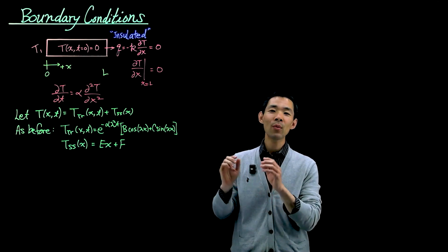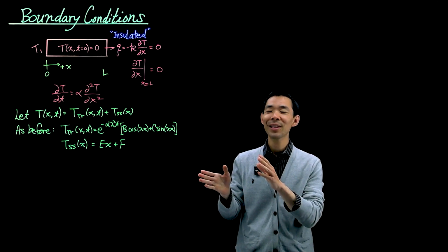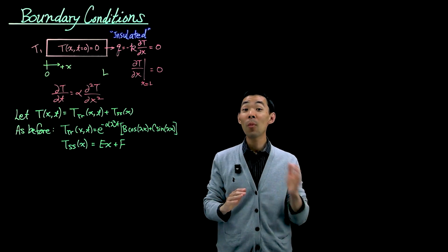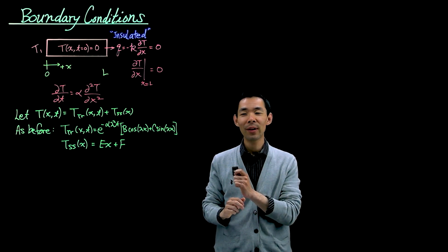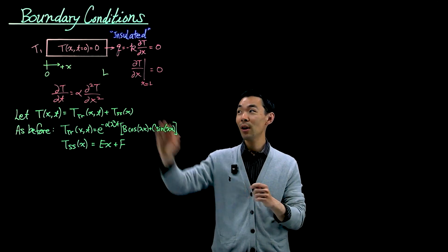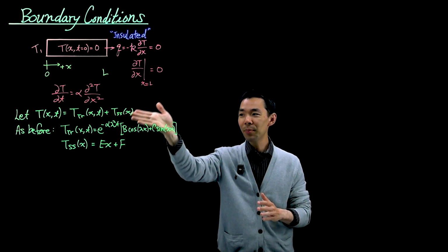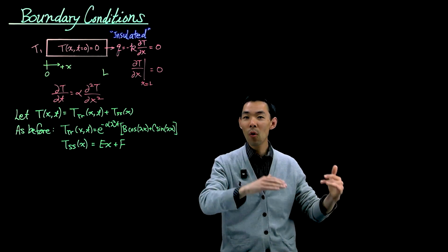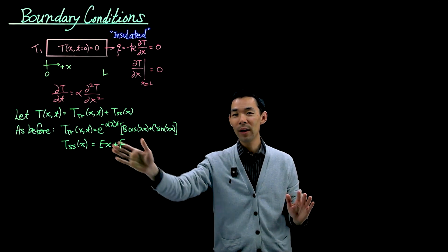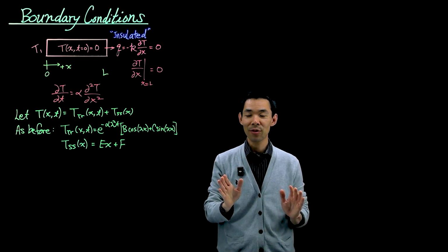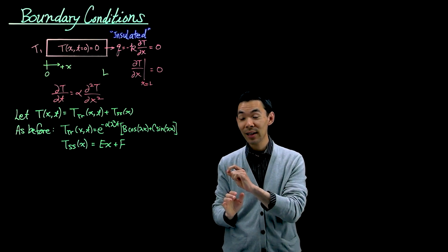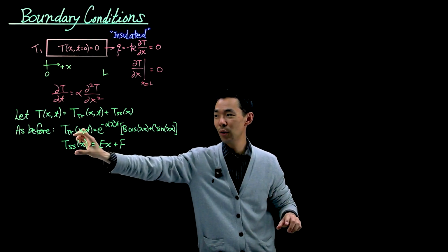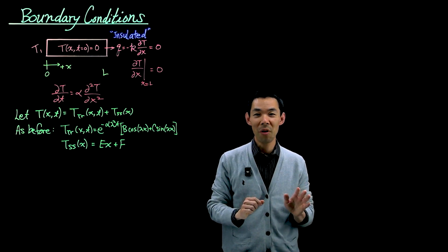Once again, the reason we're able to just write down these solutions is because the governing equation written right here has not changed at all. If you go back to your notes from the very first time we solved the heat equation, to the last lecture where we solved it for the non-homogeneous boundary condition, up to the stage where you separate the variables and get an ODE for x and an ODE for time, the whole procedure is the same all the way through here. So nothing has changed. Of course, in the last lecture we had the steady state solution that we had to solve separately. So this part is new, but the transient part is the same all along.